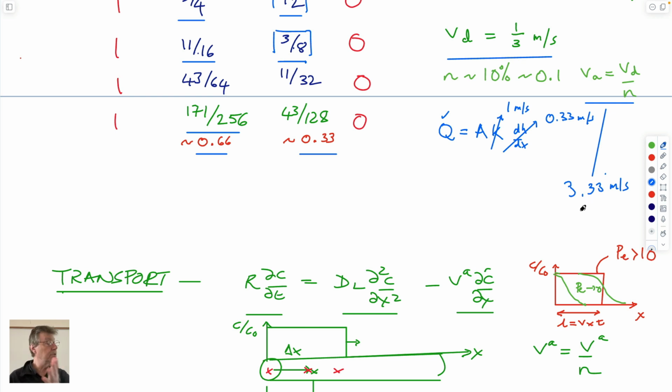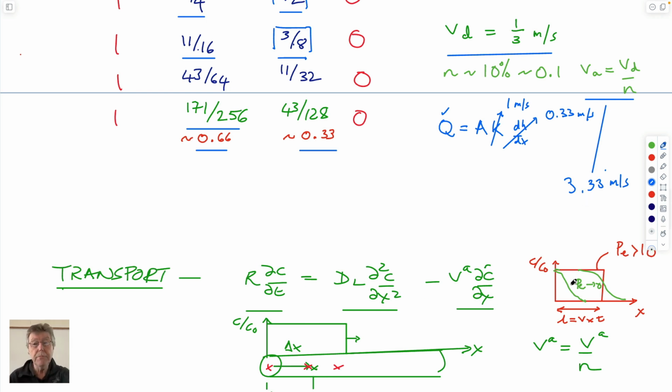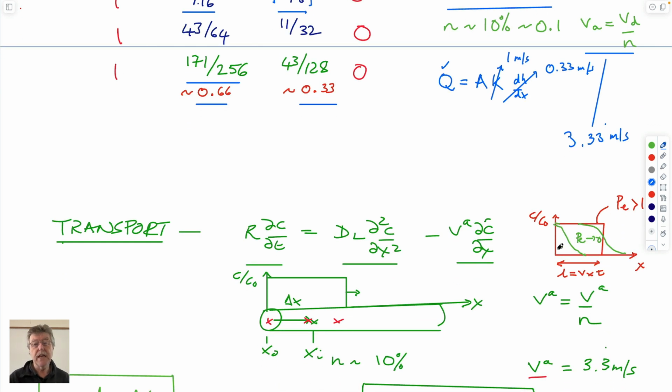for contaminant transport downstream. We had these simple models, you remember, right? That gave us how far it would travel in a given time. If you know the advective velocity and the time taken from when it was released to the time you're looking for it, that length is just the advective velocity times time.